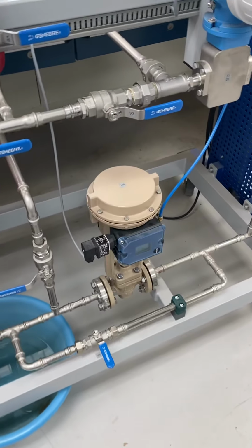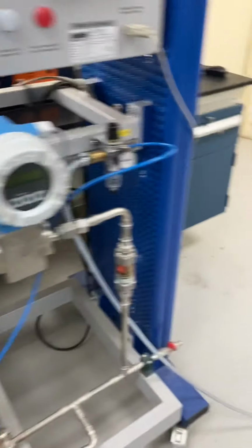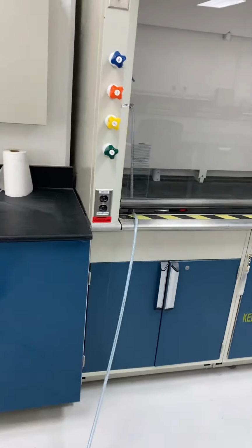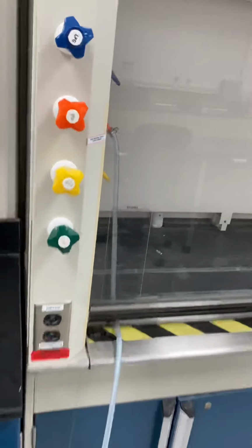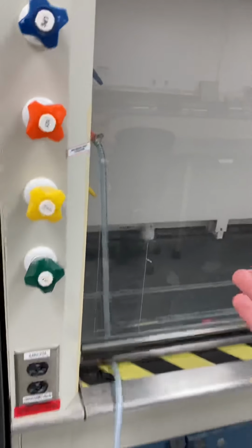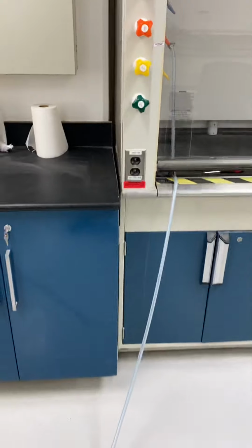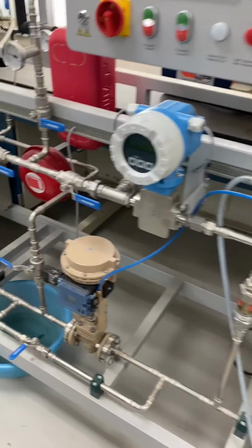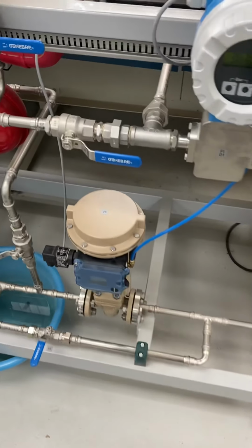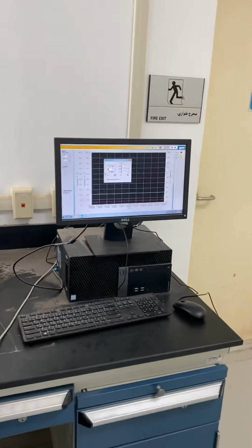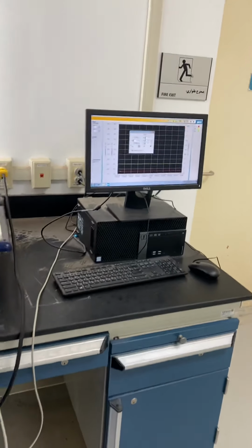guys. Okay, as we said before, this valve is pneumatically operated, opens and closes by means of the compressed air supply that comes from here. So the question tells you that if something went wrong with the compressed air supply system, which is basically a compressor and etc., if that system failed and that failure caused the air supply to the valve to stop, what is going to happen to the process and how the automatic controller will respond to the change in the process.